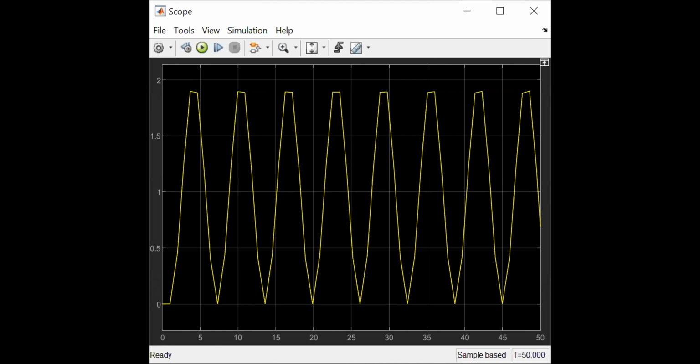Bias will stay 0. But the frequency is going to be 1. And I'm going to click OK. And once that is done, I go back to my MATLAB Simulink canvas and change this time to 5. And now run.